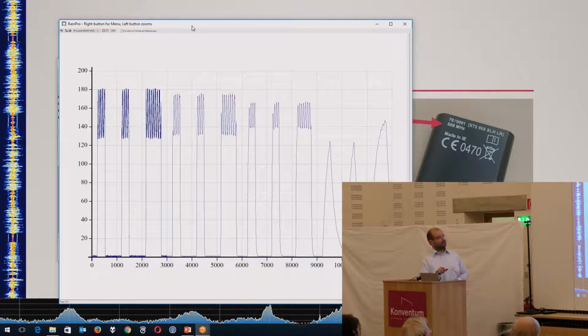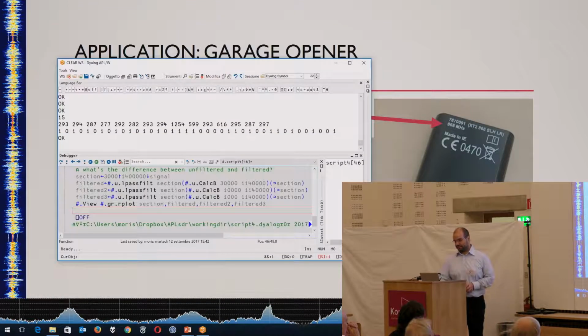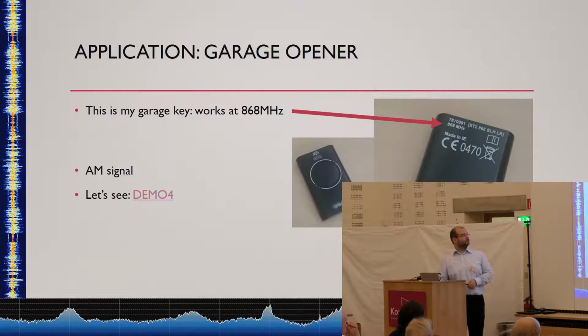If we filter it, we get that it gets lowered. The peak stays where it was. With this particular filter, if we get a window too big, however, we get undesired effects. In this case, filtering wasn't really important because the signal was clear, we could just put a threshold. However, in other applications, it might be important.